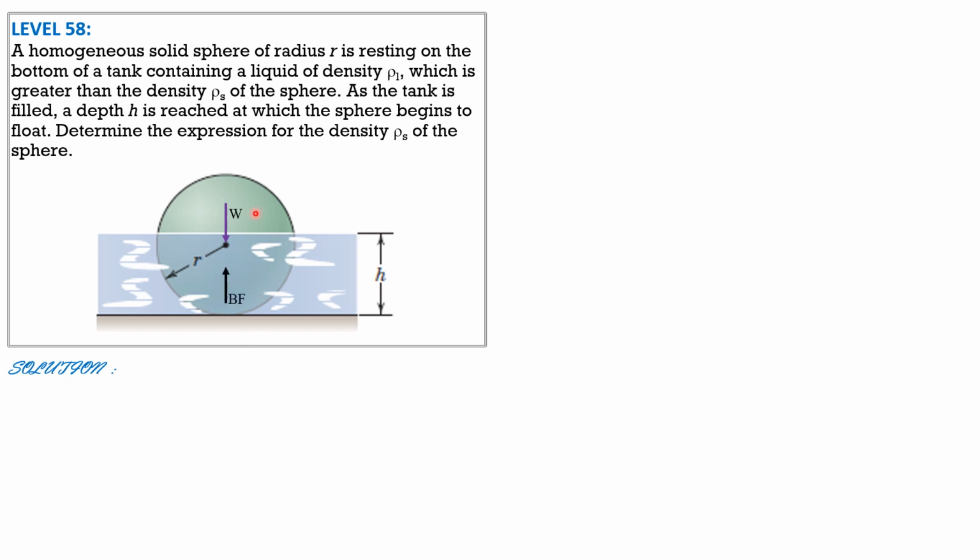Weight is the specific weight of the sphere, rho sub S times g, times the volume of the sphere, 4/3 pi r cubed. Buoyant force is the specific weight of the liquid, rho sub L times g, acceleration due to gravity, times volume displaced.